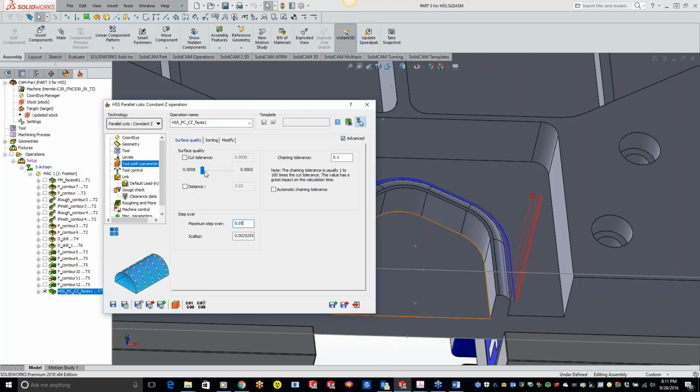So now the cut tolerance, kind of basically showing what's going on here. Like I said, a lot of this is already set up as default for you guys, so there's not a lot of stuff that you'd really have to change. But if you wanted to tighten up the tolerance or loosen up the tolerance, you can see what's going on down here in the bottom picture, kind of smoothing stuff out. And we're taking this to the extreme here with this picture, so you're not going to see a bunch of mountain ranges on your part.